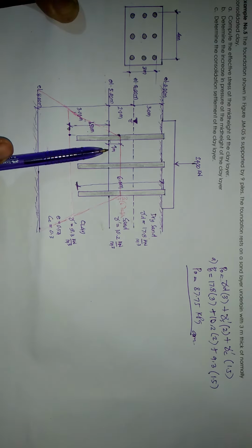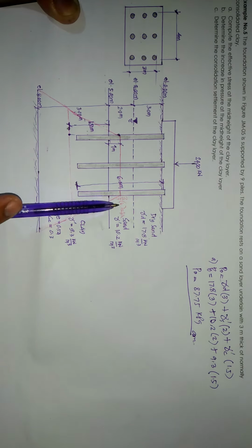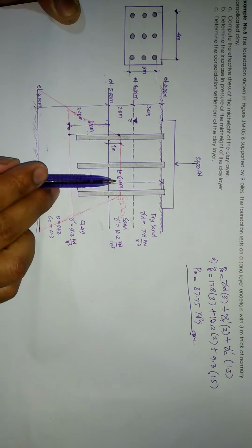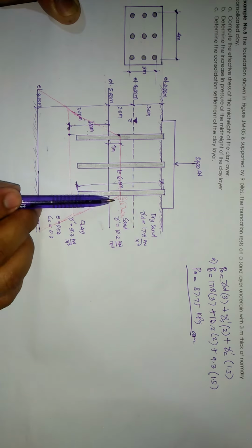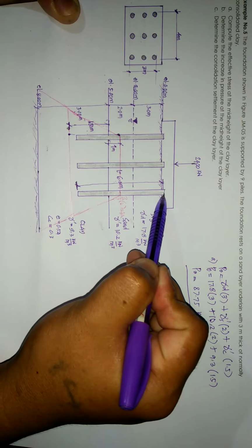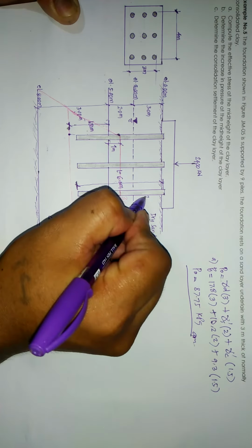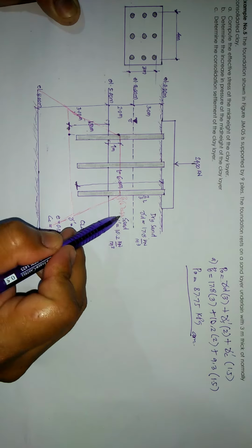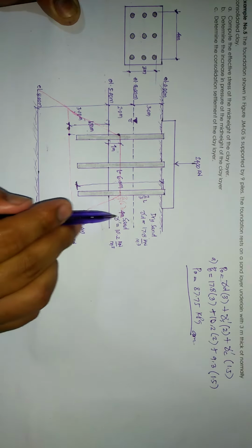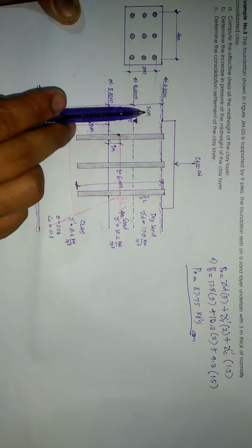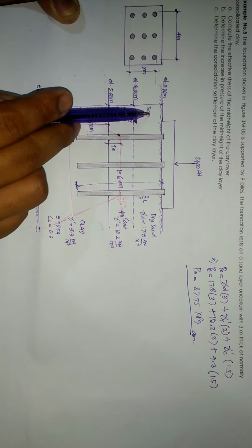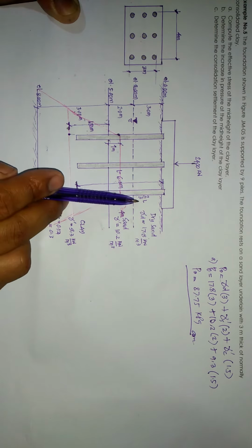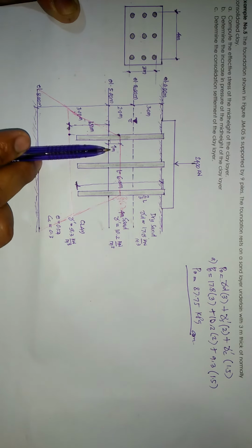Okay, bakit na naman naging 1 meter yun? Kasi sabi ko nga, yung 2/3 ng length of pile, ito yung L mo kasi, length ng pile mo is 6. 2/3 ng 6 is equal to 4 meters. So, ang basis kasi natin sa 2/3 of L is hanggang dun sa pile length natin, pababa. So, 4 meters yan, 3 meters kasi to, and then 2 meters to. Siyempre, 5 siya, andito siya nag-line. Okay? So, 3 plus 2, 5 minus 4 meters of 2/3 of L is equal to 1 meter.